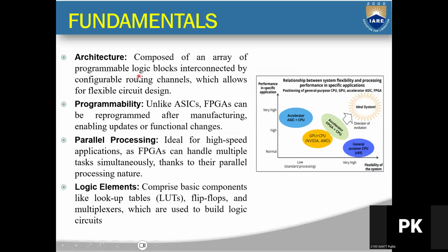Fundamentals. What are the fundamentals? Let's go through the basic fundamentals. It is about architecture, programmability, parallel processing, and logic. Architecture: first, an array of programmable logic blocks interconnected by configurable routing channels, which allows for flexible circuit design. Programmability: unlike ASICs, FPGAs can be reprogrammed after manufacturing, enabling upgrades or functional features.